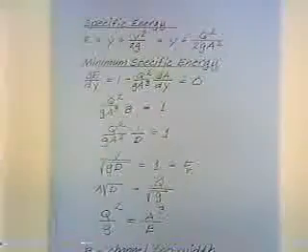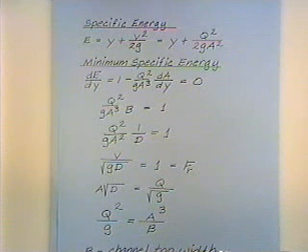If we take the concept of the specific energy being a minimum and find the depth at which the specific energy is a minimum, we can go through some manipulations and derive an equation which is used commonly to solve problems. So on this page of notes, we've written the specific energy, and it's the depth plus the velocity head.